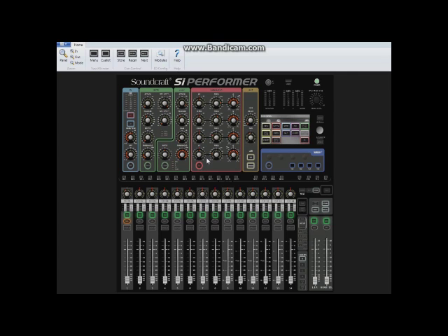You have high filter, mid-range, low mids, low filter. This is the frequency of the filter that you're going to adjust. This says whether it's the high frequency filter, the mid band, or the low mid or low frequency. And this is how wide a part of an octave you are adjusting, and it will change its width. You can see that's going to be real narrow and that's going to be real wide.